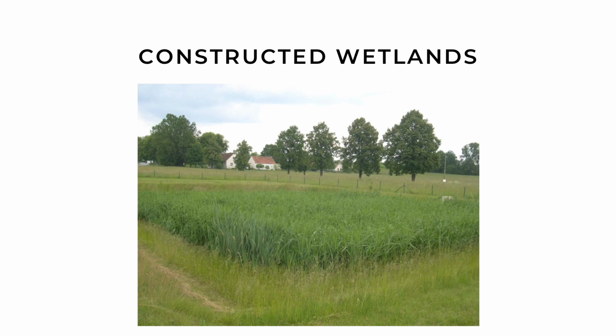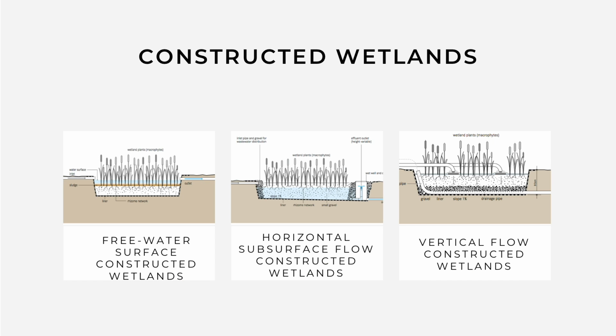This treatment technology is particularly suited for warm climates, but can also be designed to tolerate cold periods. Because of its capacity for removal of pathogens and nutrients, constructed wetlands are used as secondary treatment and polishing step. I will explain to you 3 types of wetlands.